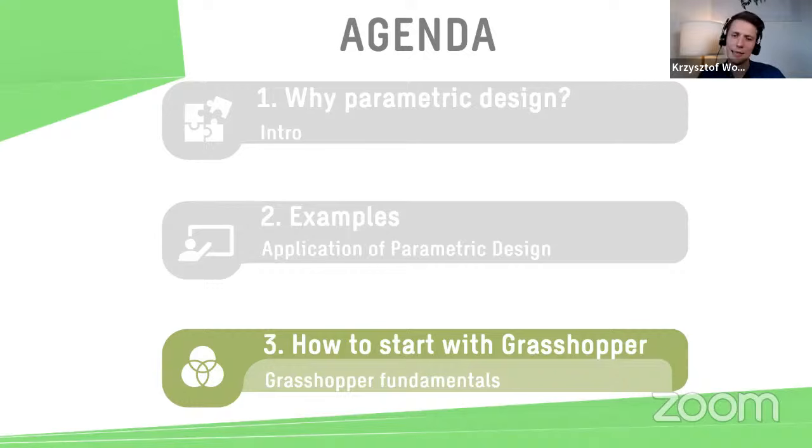I haven't tested the Idea Statica connection to calculate that. However, my colleagues got a really good result by sending it through Grasshopper to Idea Statica, getting the calculation results, and coming back to Tekla to apply the solution. So it's possible, and many companies are starting to work with this workflow.